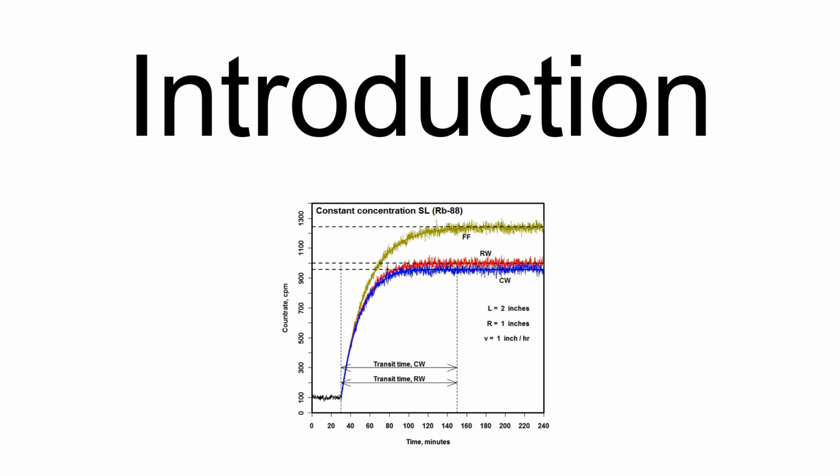There are also gas monitors which pass the air through a sample chamber volume which is viewed continuously by a radiation detector. Radionuclides that occur in the gaseous form, example 85Kr, are not collected on the CPAM filter to any appreciable extent, so that a separate monitoring system is needed to assess these nuclide concentrations in the sampled air. These gas monitors are often placed downstream of a CPAM so that any particulate matter in the sampled air is collected by the CPAM and thus will not contaminate the gas monitor's sample chamber.